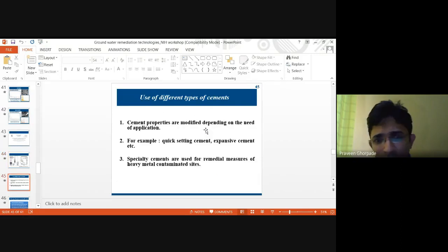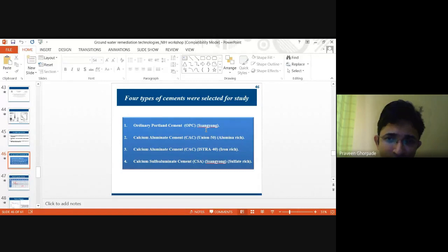I ended up developing or designing different types of cements, depending upon their properties. So there are different types. All of us know that there is something called ordinary Portland cement, OPC. These days getting OPC is difficult, because most of these cements are blended with pozzolanic material. So we call them pozzolana blended cements. Getting pure OPC is difficult these days, actually. You know that it is blended with fly ash and other pozzolanic material. So we get pozzolana blended cement these days.